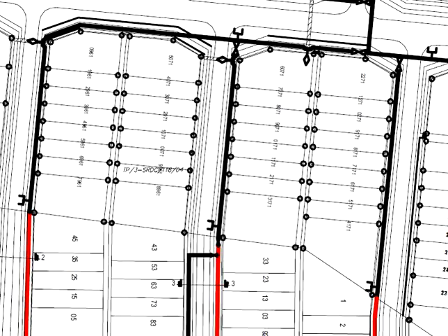Also, if you observe the existing water reticulation system, assuming this area is not developed yet, the development ends here towards the lot boundary. Since your intention of having the water reticulation systems is to supply every single unit of the building, by right, you don't have to end your water reticulation systems at the boundary of your lot.